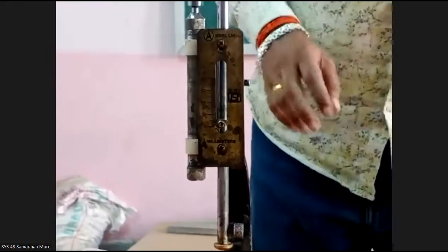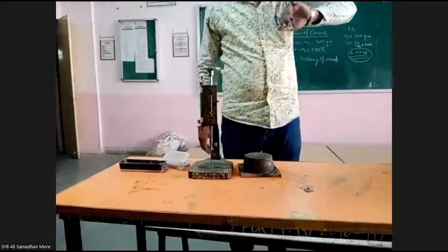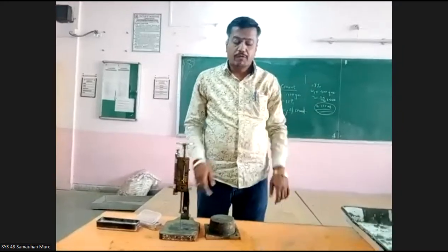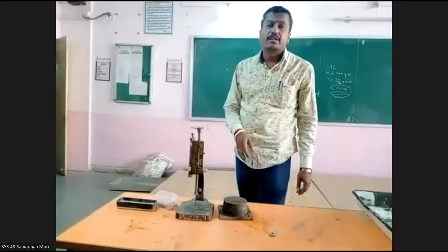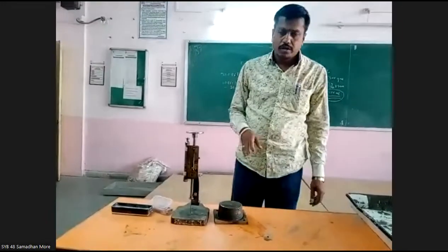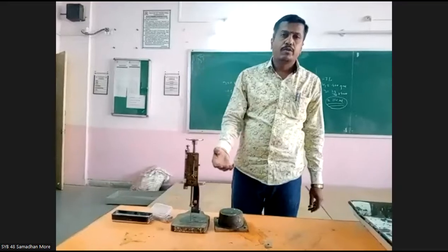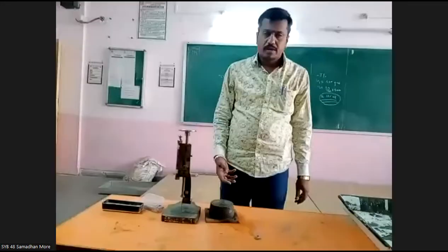So it's 11:20 on the clock. So exactly at 11:40, or 11:50, we will check whether the penetration we are getting is 5 to 7 mm from the bottom or not. Again, if we are not getting it, then we are going to check again after 5 minutes, 10 minutes, or 15 minutes. And the final setting time, we are going to check within 10 hours.